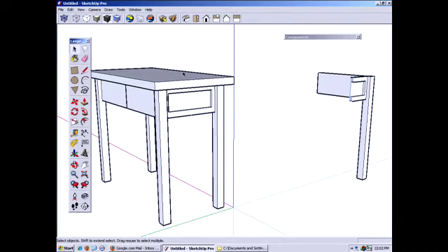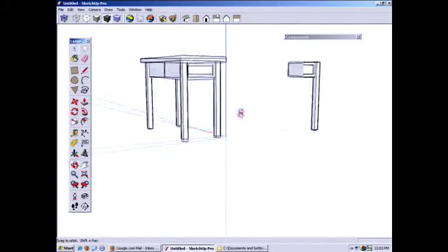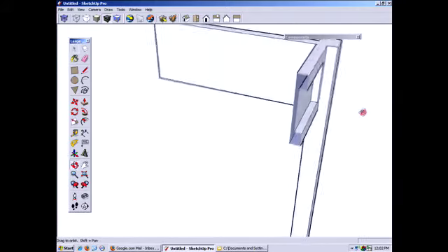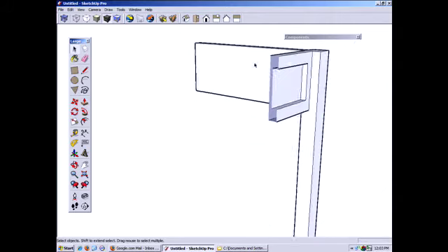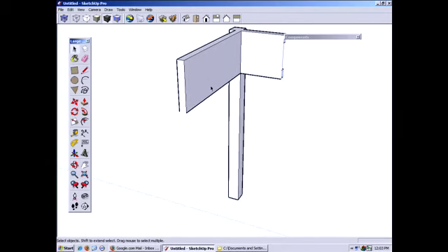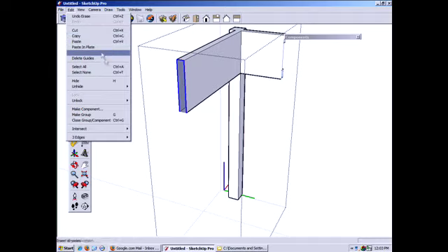Here's a tip for you though. When you are doing this sort of thing, oftentimes, we can see it over here, we hid that inside surface as well. I have found that what works best is if you delete that surface that's between the two. You don't need it, delete it. You do need those edges around because we can't get by without those, but you delete that inside surface, select your outside edges, and hide them.